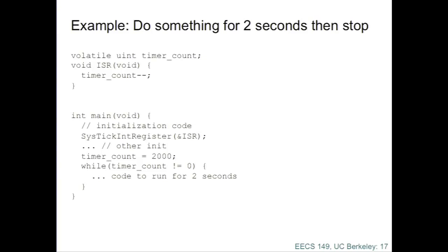Normally you have to reserve some keyword to let the compiler know that this is an interrupt service routine. Yeah. So the compiler does need to know that this is an interrupt service routine for various reasons, right? One of them is that if the compiler does optimization, it can analyze the body of this code and determine that this procedure is never called. It never gets called in the body of the code. Therefore, the optimizer could just delete that procedure altogether from the image, not include it, save some memory. So yeah, you need a compiler directive that tells it it's an interrupt service routine. Often what happens is you're given a nice GUI for an integrated development environment, and it's got the compiler built in, and the compiler is going to recognize that this line might be sufficient to give the compiler directive so that it knows not to optimize away that procedure.